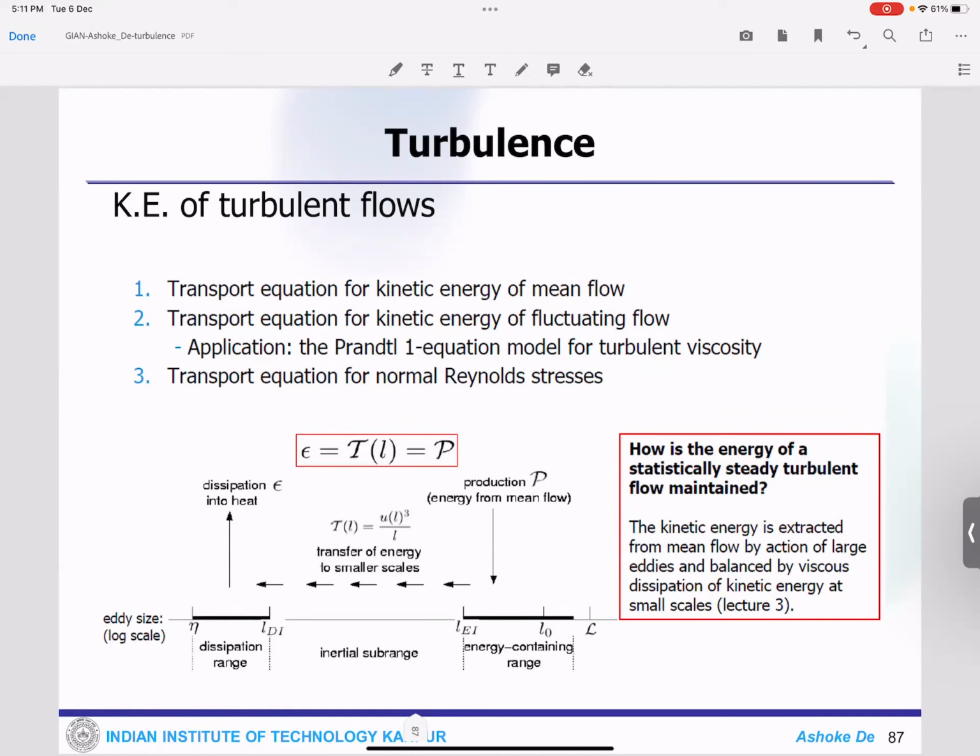And if we have something like swirling flows? Swirling flow is also absolutely wrong. There should be situations where the flow is statistically stationary, then only steady RANS might give you something, but it is going to give you only mean flow properties. Any RANS equations I have shown you are only solving for mean flow properties. I'll show that when I come in the next session. I showed you that energy diagram, which is also visible here. When you do these different modeling approaches, which model does what? I think that will also clarify more.